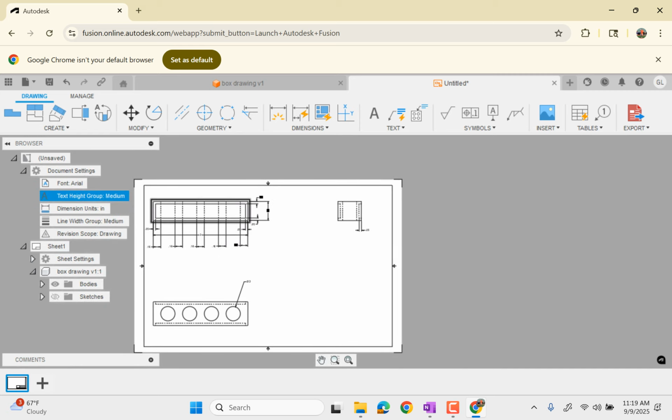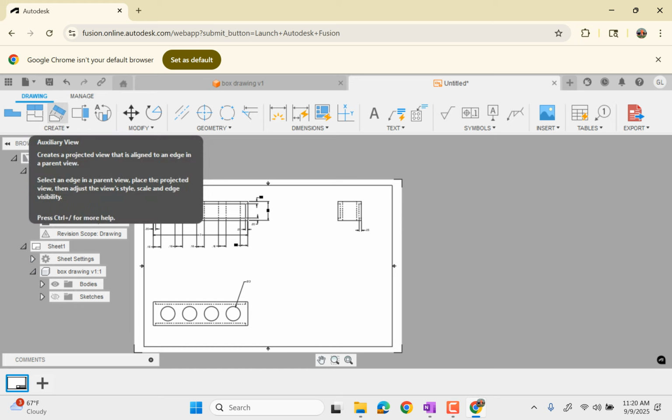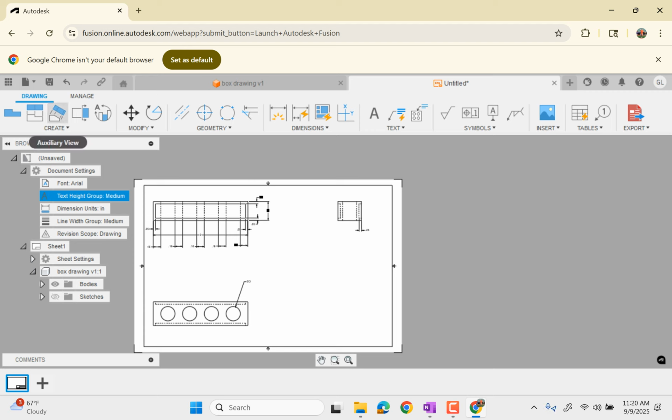I'm going to do one more thing. All of my pictures are wireframe pictures, but that sometimes makes it a little hard to visualize the part. So in that last open corner, I'm going to make a three-dimensional solid view of this thing at an angle. I'm going to go projected view of this, and I'm going to put it over here.